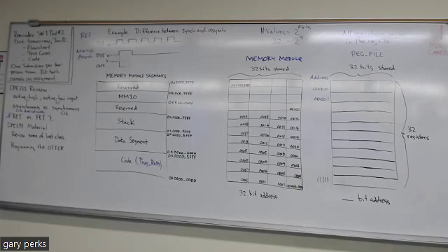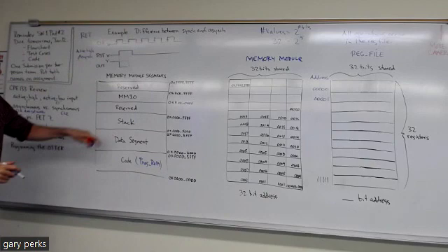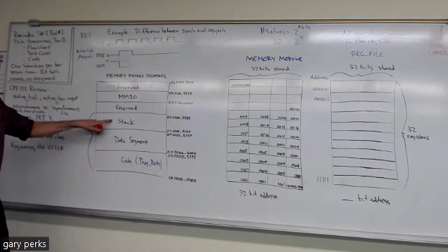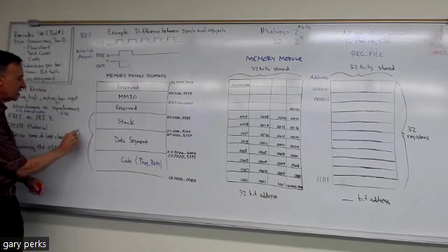Now, the memory module is more than the prog ROM. The prog ROM is part of the memory module, like embedded, if you will. And that's where your program is going to be. That's where the assembly language instructions are going to be, the 1s and 0s for those assembly language instruction sets you're going to program the otter with. Now, another thing about the memory module is these 3 segments right here. The stack, the data segment, and the code are referred to as real memory.